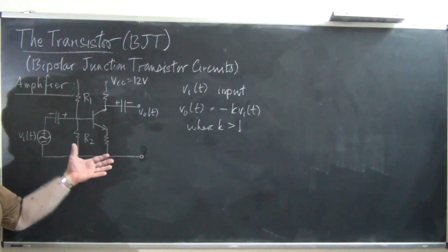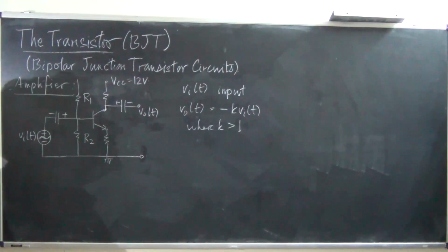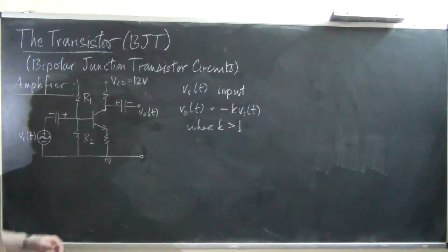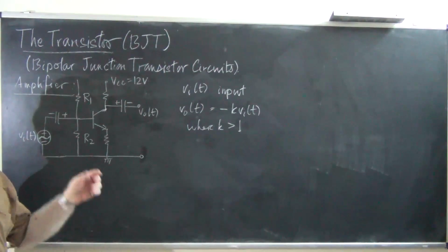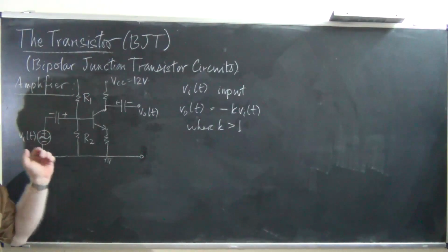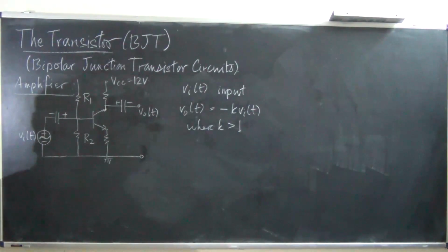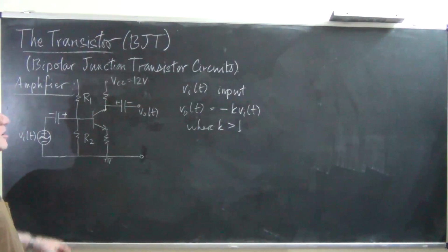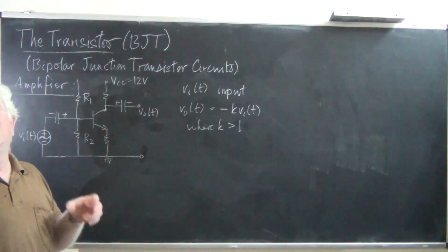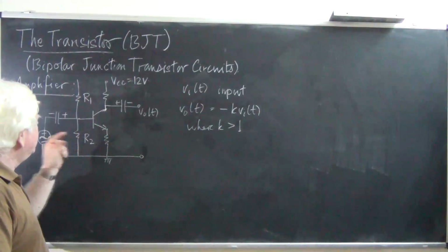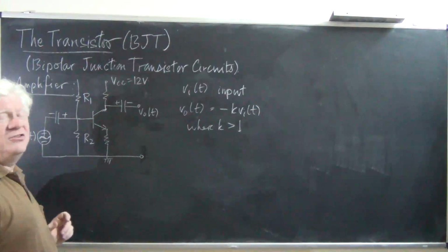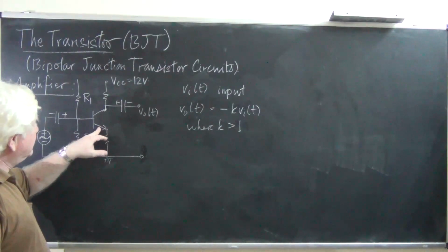Now let's get into the details. This is a more sophisticated circuit. It takes care of various other things that we have glossed over until this point of time. The first thing is proper active operation. I have already said that in order for the transistor to operate in the active region, the emitter base junction should be forward biased and the collector base junction should be reverse biased.